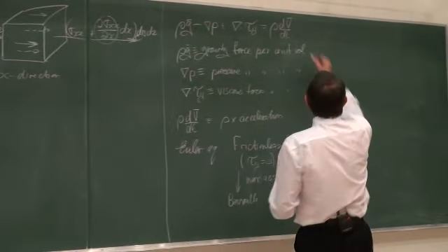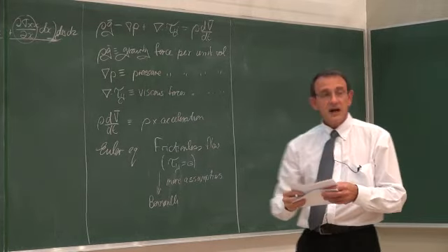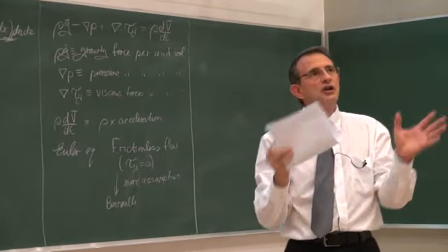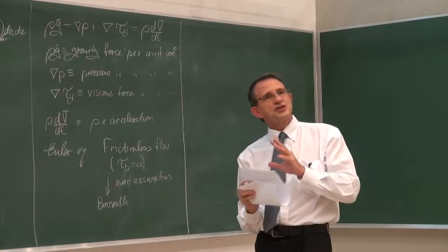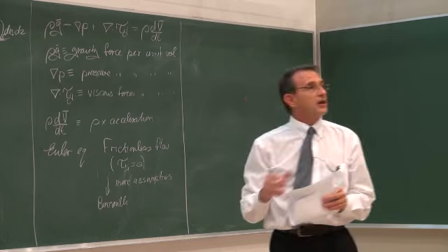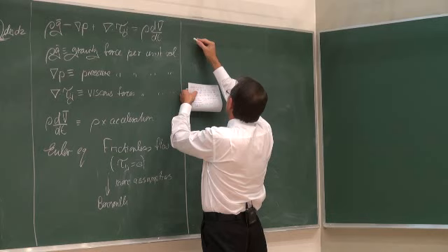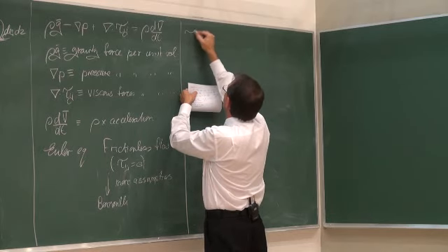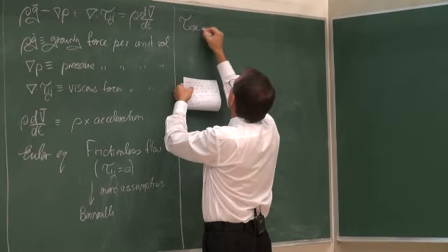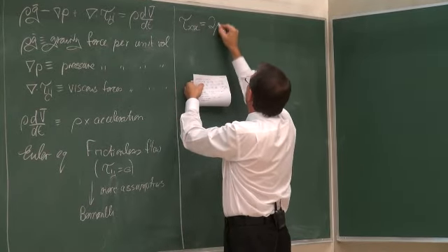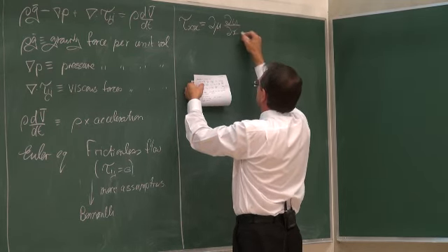Now how do we get rid of all those stresses? Well, fortunately other people did some work, and we are not going to do this derivation here, but you will see these same terms when you study strength of materials. In terms of that generalization to 3D viscous flow, it can be shown that tau xx is equal to 2 times the viscosity multiplied by partial du dx.